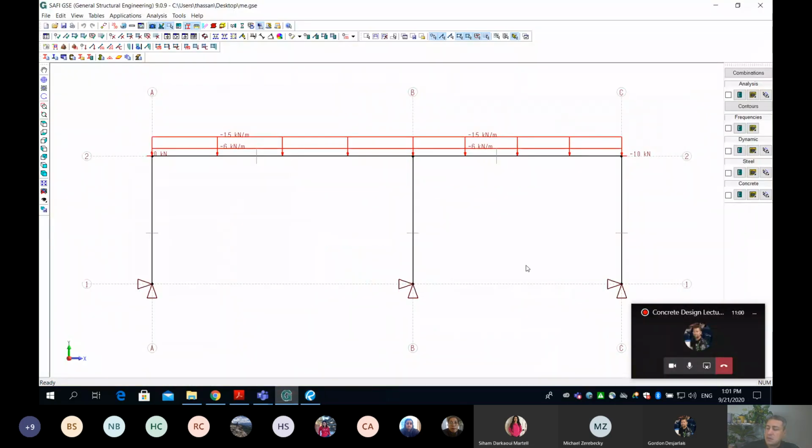And if you guys want to remember, we are able to create grid lines, add joints, and then join those joints with members, and then assign those members properties. When I say properties, I'm referring to two different things. One is the material. Number two is the shape of the cross section. So this is assigning the properties to my member. Then once you finish this, you also add the supports wherever the supports will be available for the structure.